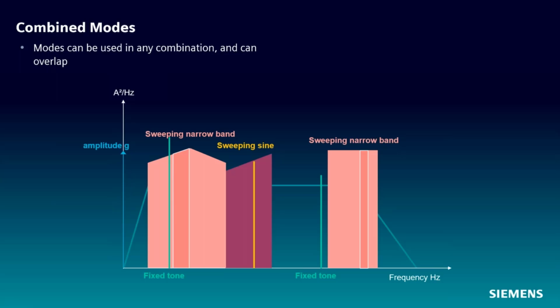If you don't define that in the test, there'll be a warning that says it's good practice to have your bands 10 dB higher than the baseband random, but it won't stop you from running the test, although it can be difficult to control that way. And the real reason for that is being able to separate out the bands from the base random signal and be able to control them independently.